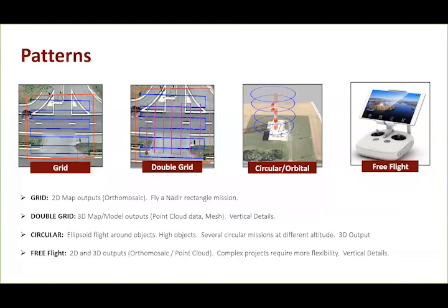So beginning off, a lot of times, that's why some of the autonomous flight programs for grids and double grids help assist you work through that, because there are preset values. And again, a lot of the photogrammetry programs will guide you on what they're looking for to successfully process it through their programs, and so that can help guide you when you fly by stick or with any of the presets that are available.